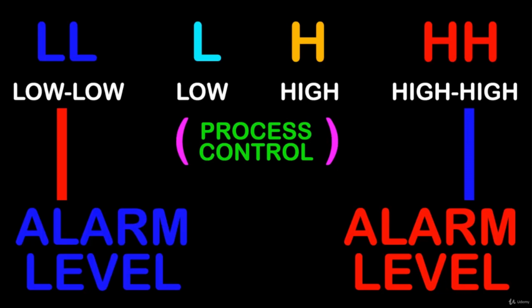And we exceed our 80-degree set point, and maybe once we get up to 90 degrees, we have a high limit set in our program that notifies the operator there's a problem, something's wrong, and again, possibly it interrupts the process, or possibly it has a way of cutting the heat somewhere upstream, maybe at a power supply that isn't dependent upon that relay for control. So this is an important concept to understand when you're programming, and it's a normal, frequently used part of process control.